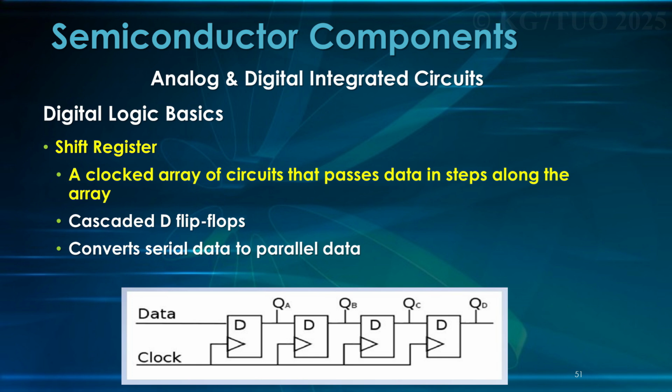That can be useful because we've got all kinds of different connections now, and serial and parallel don't work together unless you have something to do it. When it comes to computing devices, does everybody understand the difference between serial and parallel? I see no hands. Okay, so here's the deal. Serial devices, and we're talking about everything from USB clear back to 232 and 422 devices, all send pulses down a single wire, one after the other after the other.